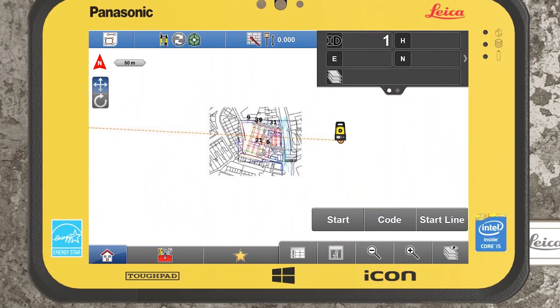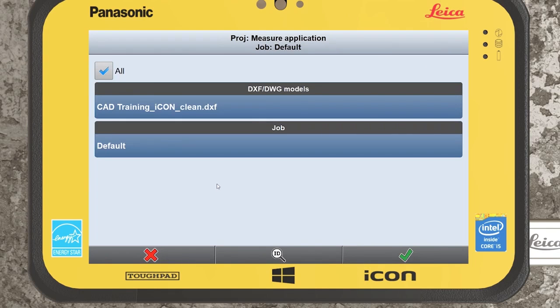Some of you may ask, okay, if we want to look at our points, so our survey points, any imported control points and so on, you can see what looks like an Excel spreadsheet down here, or a tabular grid. If we click in here, this is our point list, but it doesn't go straight into the point list. It brings us first to this section where it says, which information do you want to show the points for?